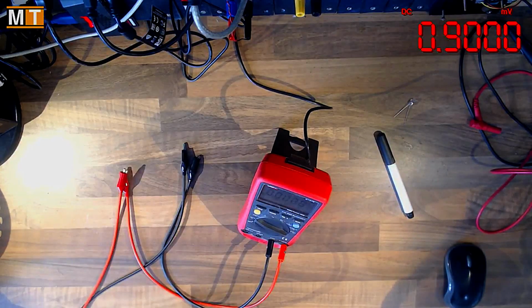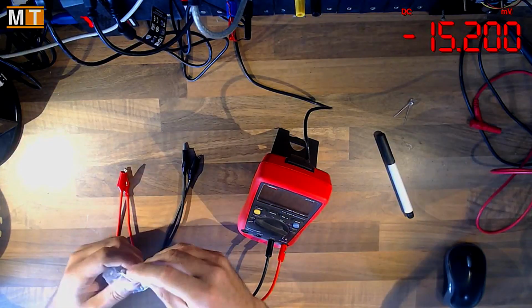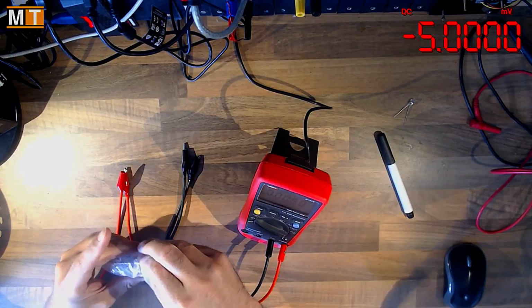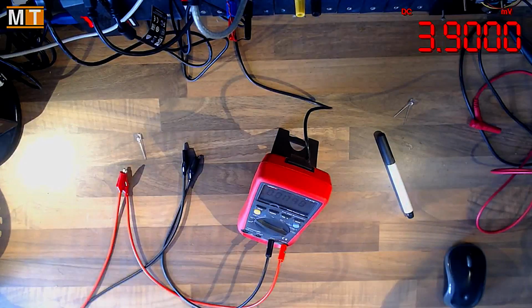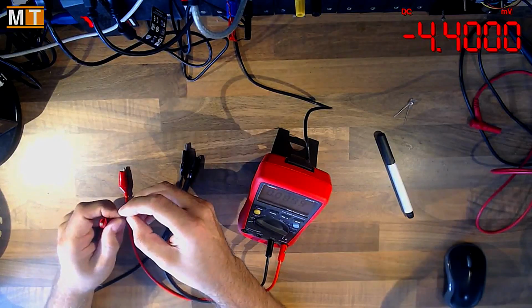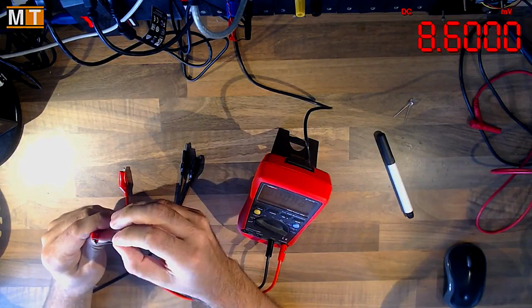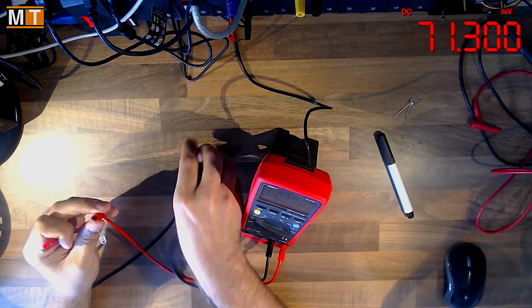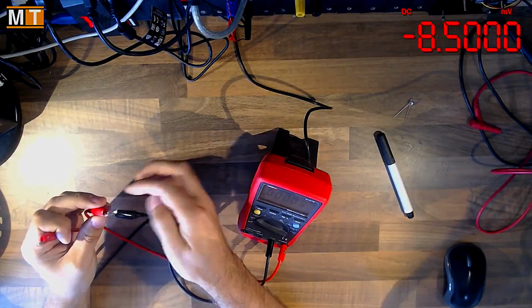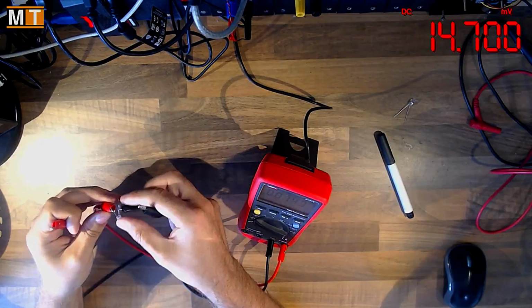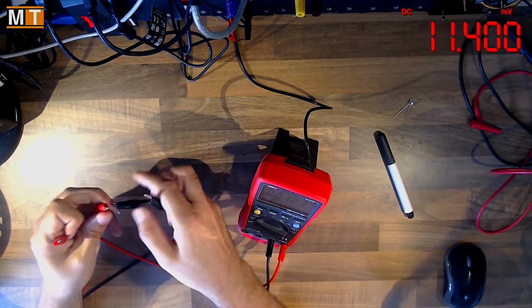Okay, what happens then? We know the forward voltage of one of these LEDs is about 1.7 to 2 volts. If I set my power supply to 1.9 volts, but 1 amp, what do you think is going to happen to this LED? We're allowing a huge amount of current through it, far, far more than the LED can cope with. But limited to 1.9 volts, which is at or just below the forward voltage at 20 milliamps.